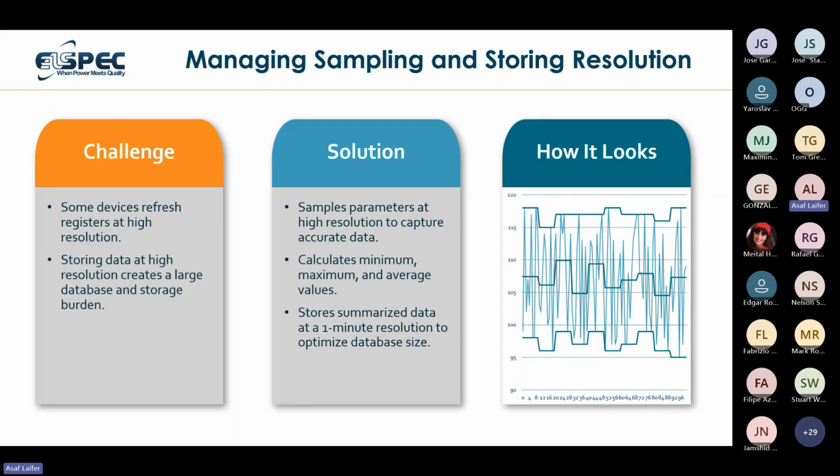So you have two options to overcome it. One is to ask PQSCADA to fetch data not every second, but every minute. But then you're missing all the data in between, right? You don't know what happened between each and every minute, because it's sampling once every minute, and between two minutes, you lost 60 samples.